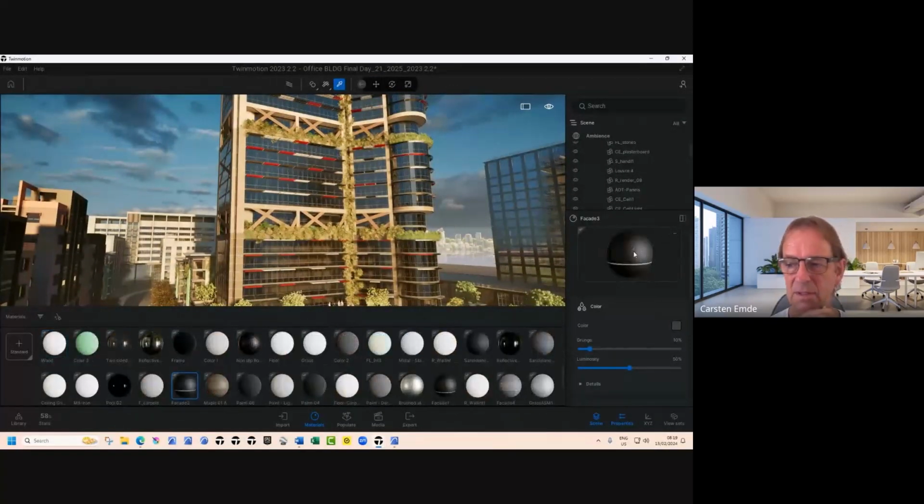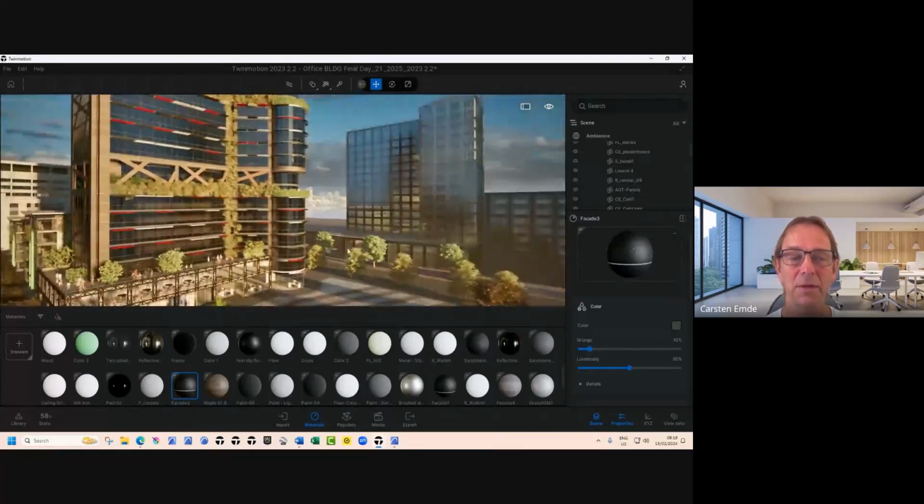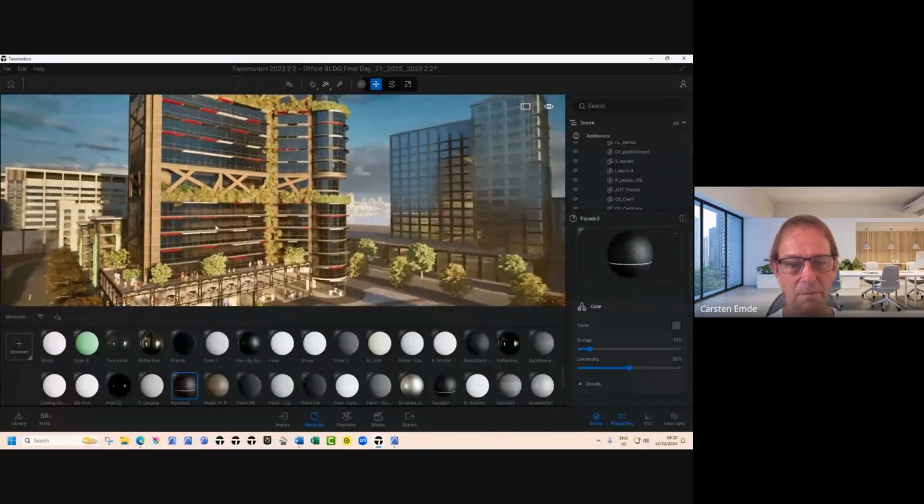So I just pick this material and you just move it back in here and move it back to the top. You got the same material. But again, you got a lot more flexibility by splitting it a little bit further up in your CAD system. So I think that's, yeah, I've worked like this all the time because I know from experience that clients come back and they will maybe think, oh, can you change this and that? And then if you haven't split up the material, you'll have to go to ArchiCAD and split it up, or Revit, whatever. Anyway, so that's sort of the material split up as a little tip.